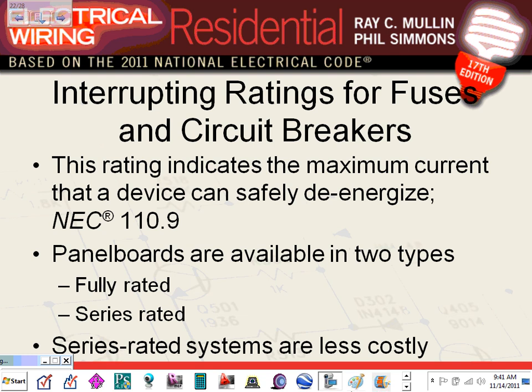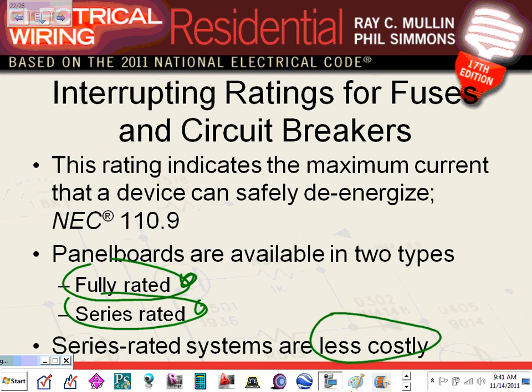This concept, fully rated, as you said, guys, some of you have never heard of it. Fully rated and series rated. The reason we have fully rated and series rated is only one reason, right here. Less cost. That's the only reason why we use series rated equipment versus fully rated equipment.